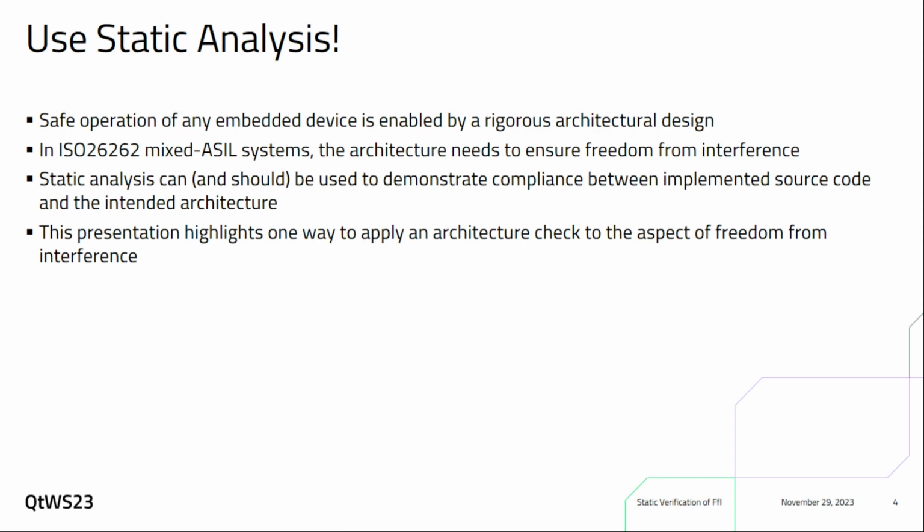And quite often you encounter, especially in the automotive industry, looking at ISO 26262, the situation that you have to assign software elements of different safety levels, different ASILs, to the same hardware element. So they have to coexist on the same piece of hardware. And you need to enable this coexistence via this property of freedom from interference. I'm going to discuss a little bit more details on the next slide.